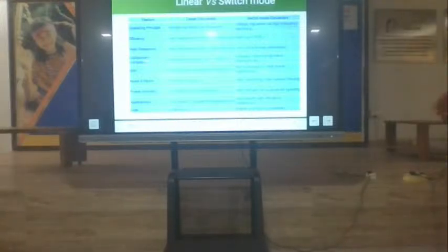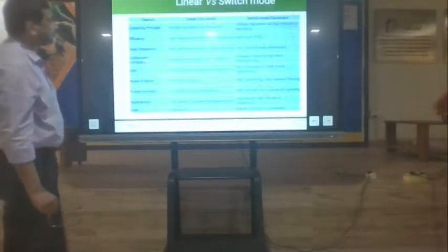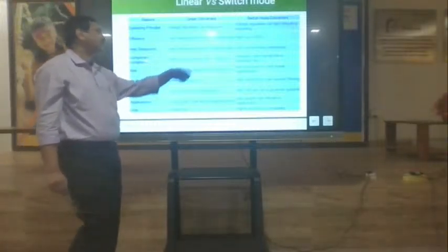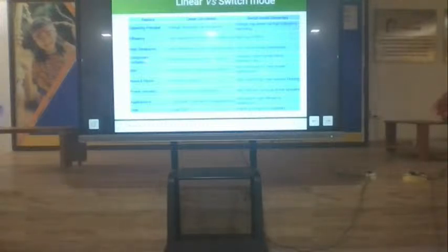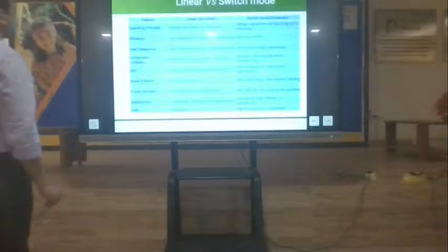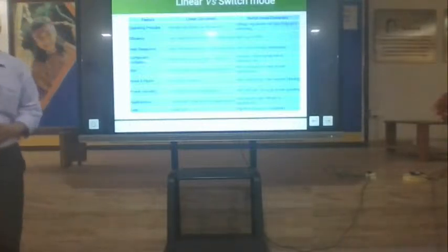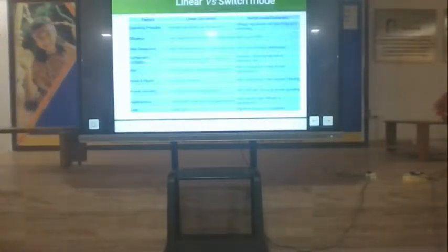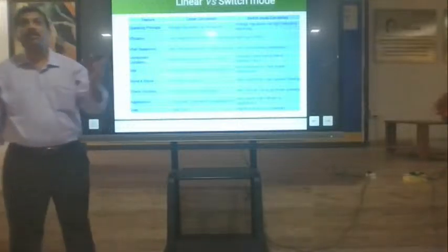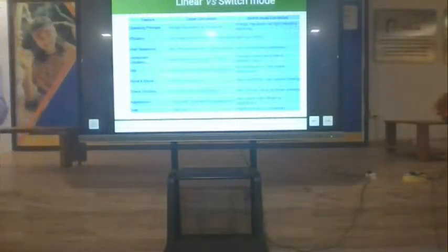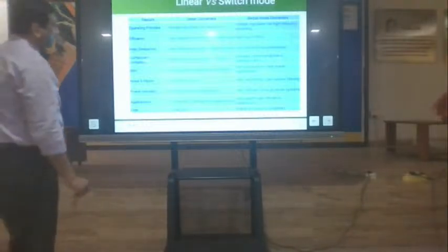Switching uses a larger number of components, where you need a controller, an inductor, a capacitor, etc. Whereas in linear, the component complexity is limited to a filter and a bridge rectifier. On size, in linear the semiconductor sizes are small, but the heat dissipation devices like heat sinks are very big.